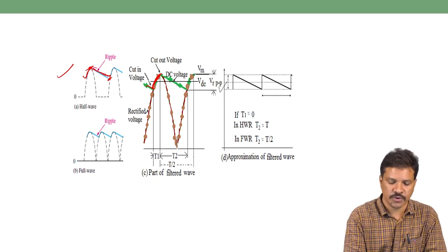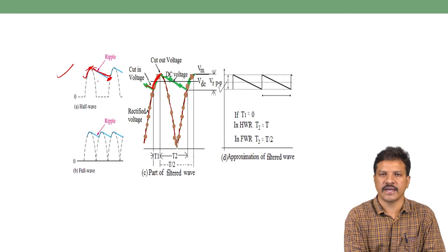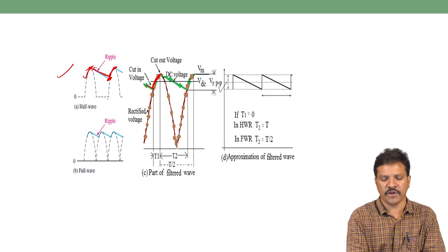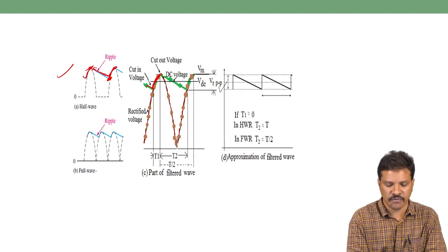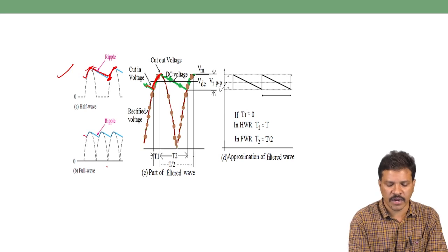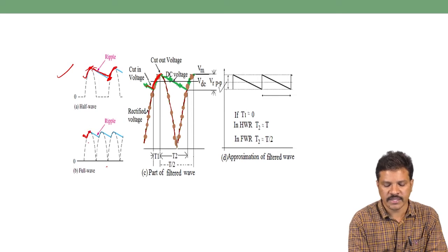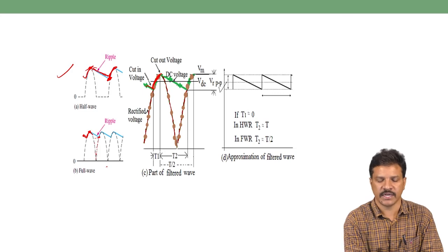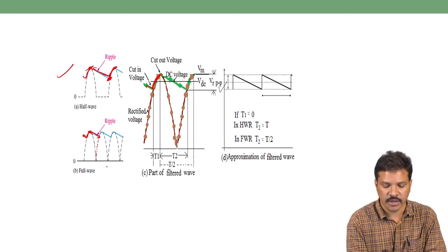Again, when the input voltage reaches the level that forward biases the PN junction diode, the capacitor starts charging. This is for the half wave rectifier with the capacitor filter. When we see the full wave rectifier, the voltage starts to charge up to the maximum voltage Vm. When the full wave rectified output gets below this maximum voltage, until the rectified output reaches the next voltage level that forward biases the PN junction diode, it will be recharged. Discharge, again charging, discharging, charging, discharging.